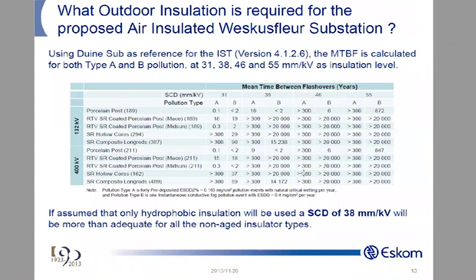Now remember, these CH3s don't like a polar thing. So what do they do? They all go outwards. So now what is around this polar thing in the middle? All these CH3s, these methyls. What are they? Hydrophobic. So there you've got a hydrophobic particle now. And that's how low molecular weight silicones migrate to the surface, encapsulating the pollution particle. And that's how they migrate into the actual pollution layer.